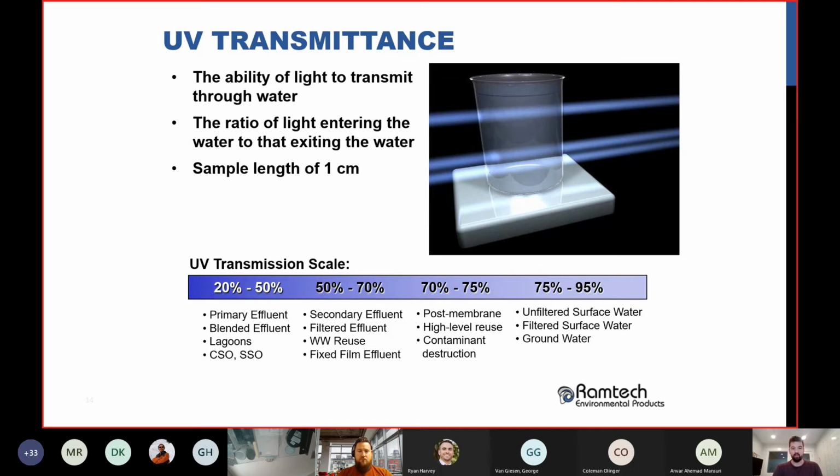For wastewater, it's very difficult to predict because every plant is different, but lagoon wastewater is 35, 40%. Secondary effluent out of a secondary clarifier, for example, 55%. MBR plants, 65 is what we usually assume, although we often see considerably higher than that, but we always size on the worst case scenario. So for MBR, 65 or so. Lots of other examples there too.